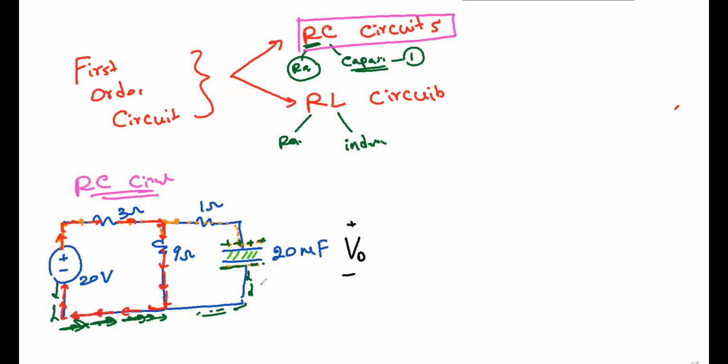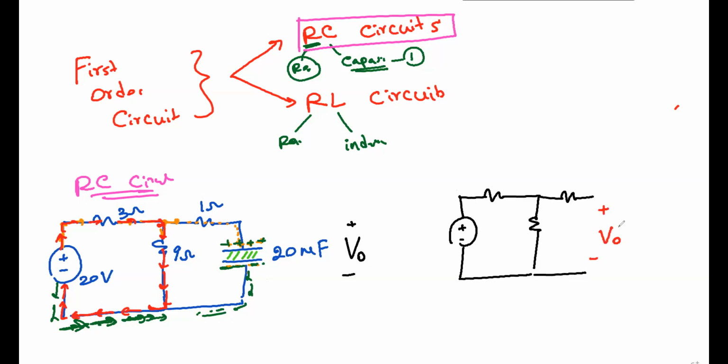When the capacitor is fully charged, there is no current going, so it will act as an open circuit. Can you remember that? So when the capacitor is fully charged, your circuit will look like this. And if you find the voltage across these 2 points, that is your voltage across the capacitor. Do you agree with me? Yeah, we're good so far. So how do we find the V naught? From last week's knowledge, you should be able to find the V naught.